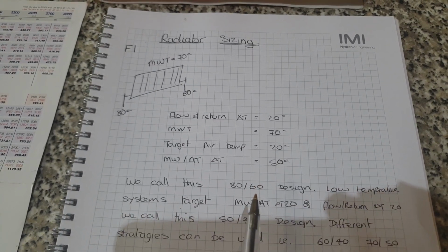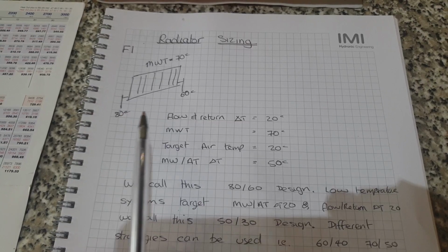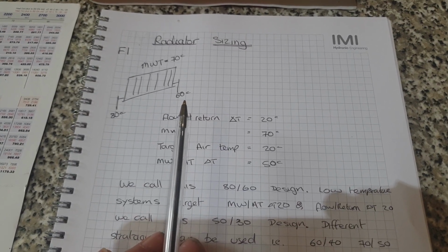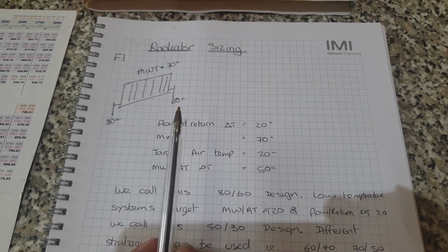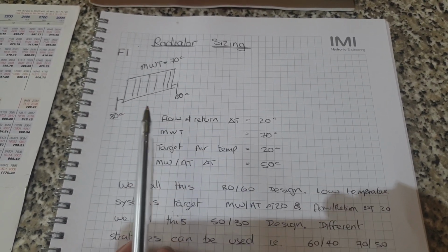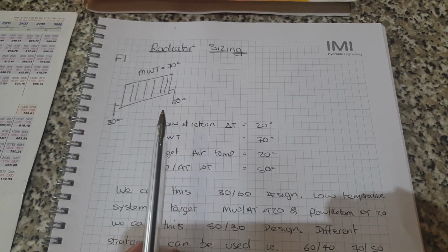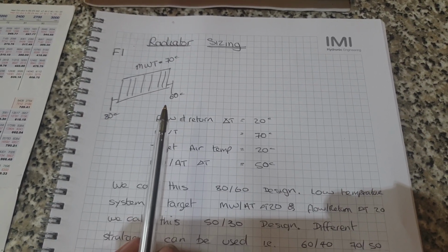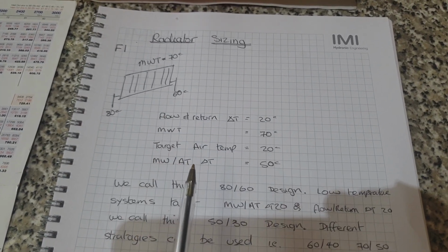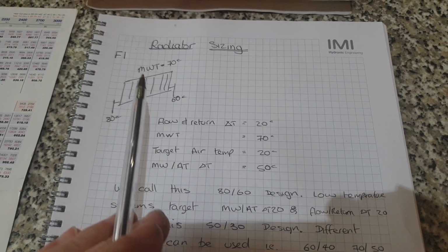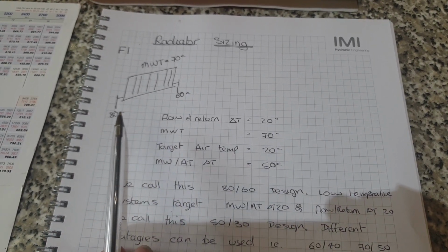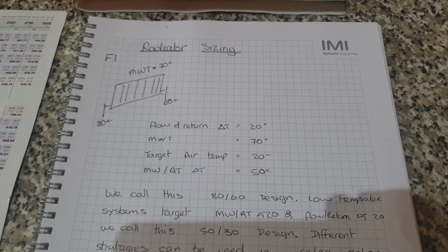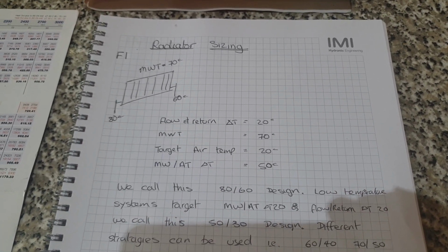Right, so if we've got a flow temperature up in these ranges here with returns of 60, we're out of condensing range for our boiler. And this is not a setting we want to set, whether we're set at a single temperature or whether we're using weather compensation. We don't want our boiler to be running at these high temperatures or to have to run at them. If we can avoid it, what we really want ideally is for the boiler to always be as close to fully condensing as possible, and for that the theoretical target is delta T 20 mean water to air temperature to room temperature, which would be a flow temperature of 50 and a return temperature of 30. Now this can be impractical in a lot of cases, and in a lot of cases you're retrofitting a boiler in an older property and you don't want to be changing the radiator.